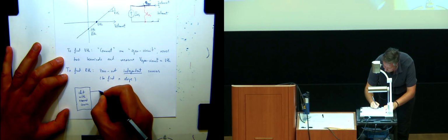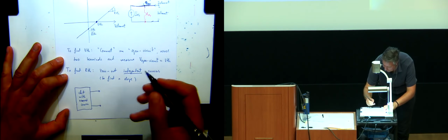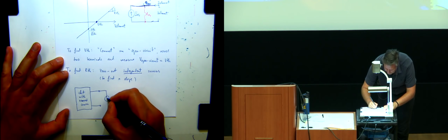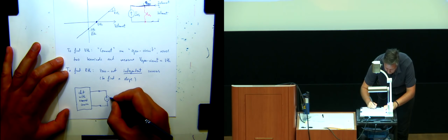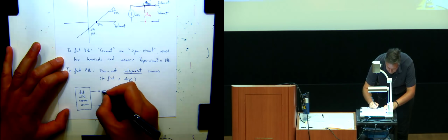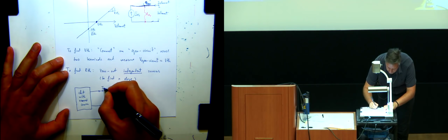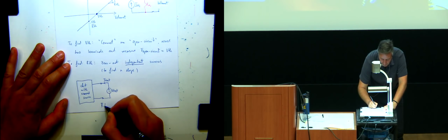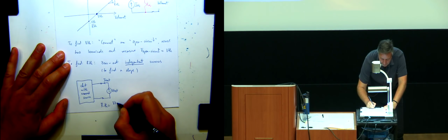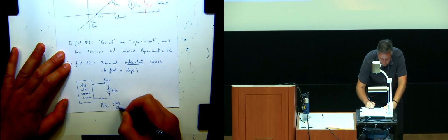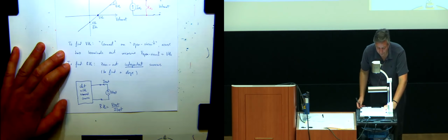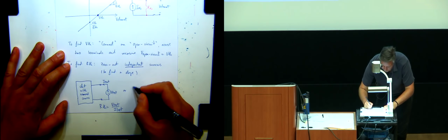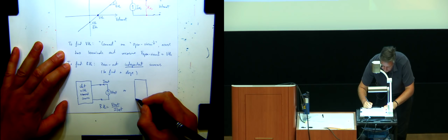And what I'm going to attach to this circuit in one case is a test voltage, and I'm going to measure current. And then my R Thevenin is going to be equal to V test over I test. In another way, we again have the same circuit.